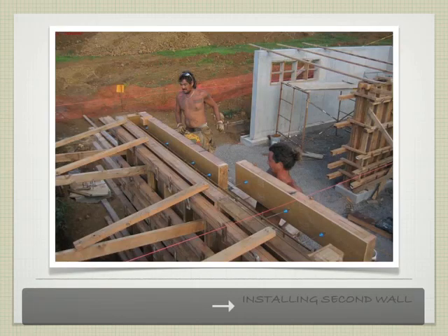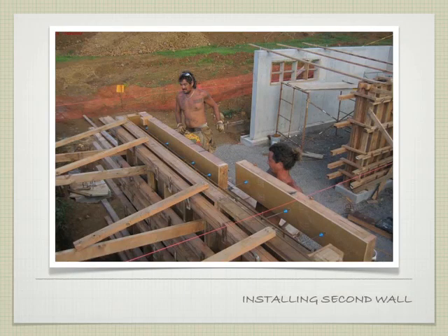So we continue on with the same set of pictures here. This was the piece that we were showing before, but it works the same way out on this side, where we have the one side of the wall that's been placed. These are those diagonal braces. We have our studs. We have our whalers running across. We have the little metal brackets that are holding the form ties in place. This is the opposite side of the form tie. It's extending out like this.